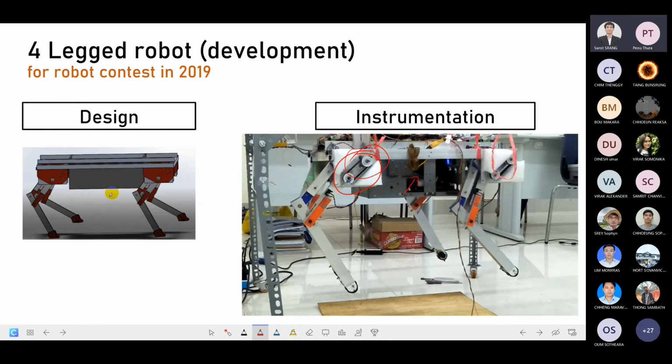The motor should be strong, with high torque but low velocity, and should be a pancake type. A pancake motor is like this, not long like this. This one is not good for manipulation, but we need a pancake with the connector like this.